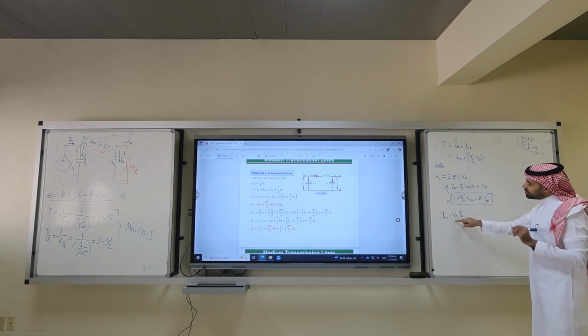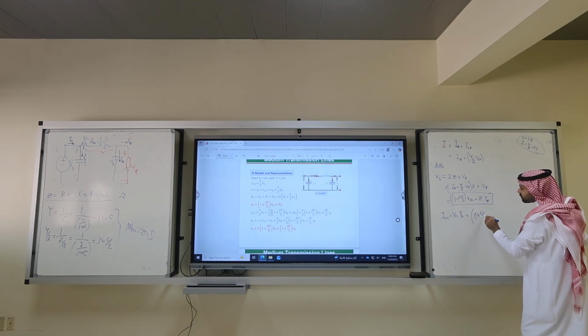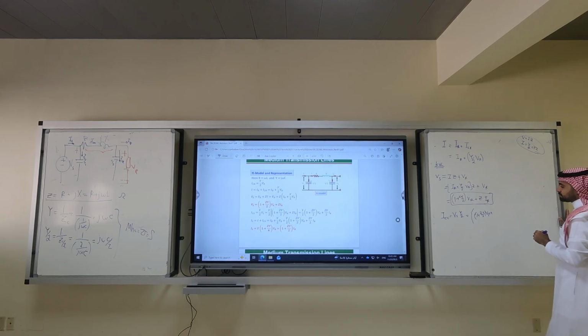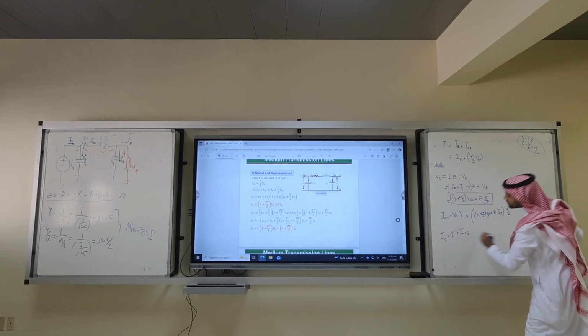But here I'm descending it, which is equal to, what is VS? (1 plus ZY over 2) VR plus ZIR times Y over 2. So what is IS? IS is I plus ICS.